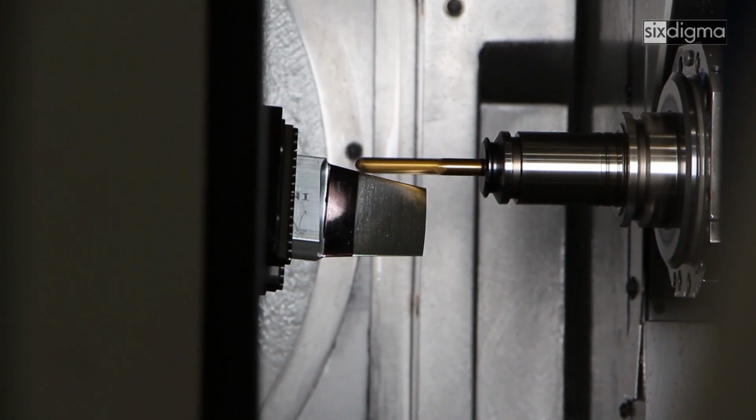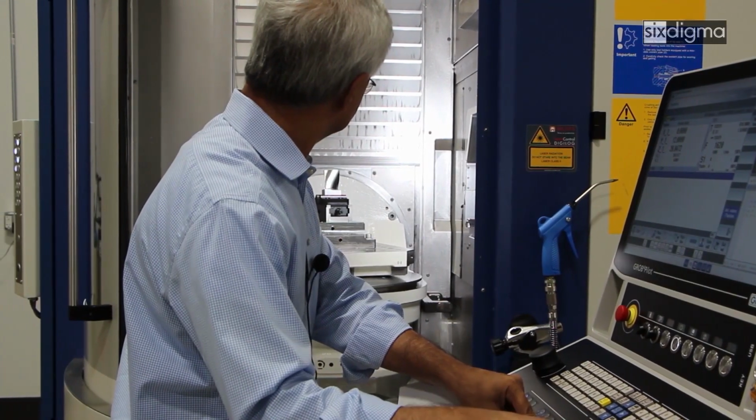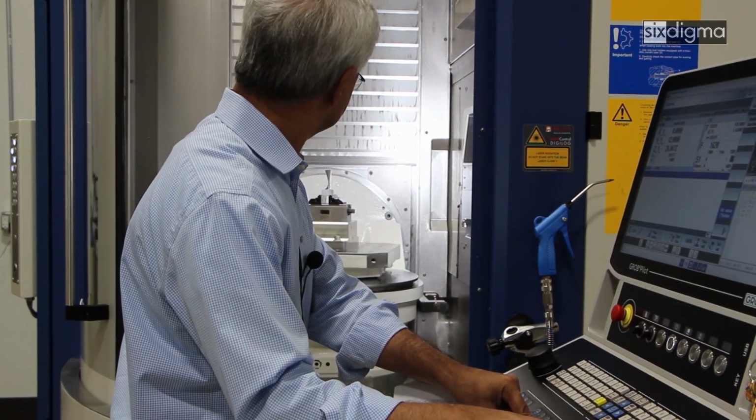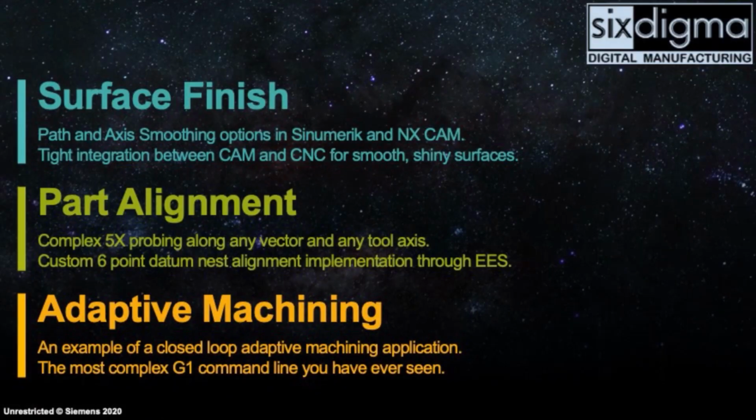As you can see, being able to exactly locate the part has many applications: airfoil repair, being able to correct coatings, being able to machine the datum surfaces of ECM'd, cast, or forged parts. This is also very useful in centering 3D printed parts inside the intended volume and machining datum surfaces.